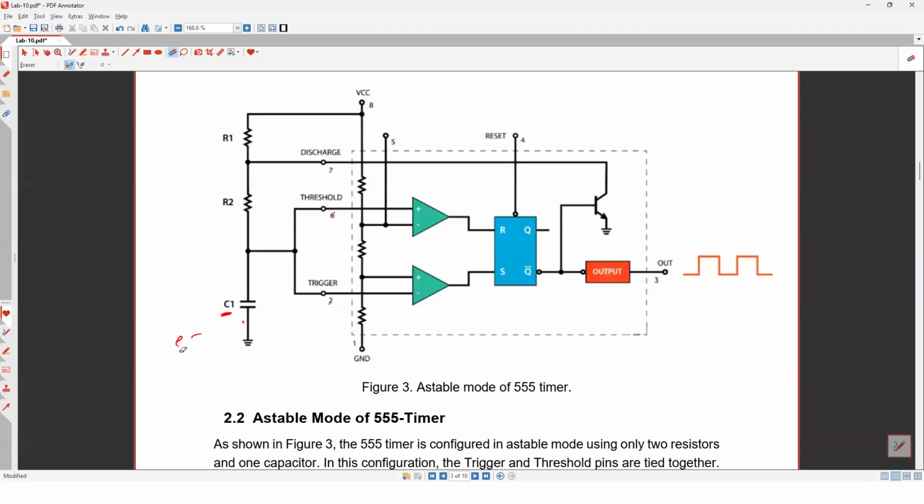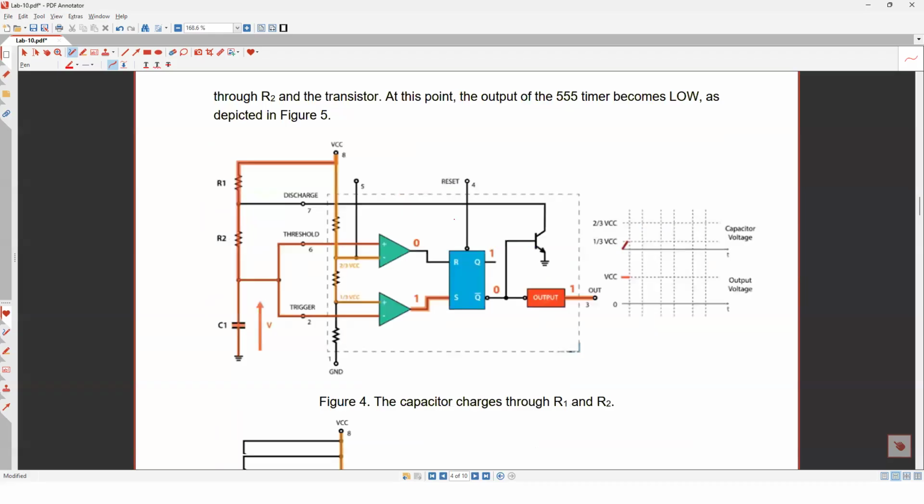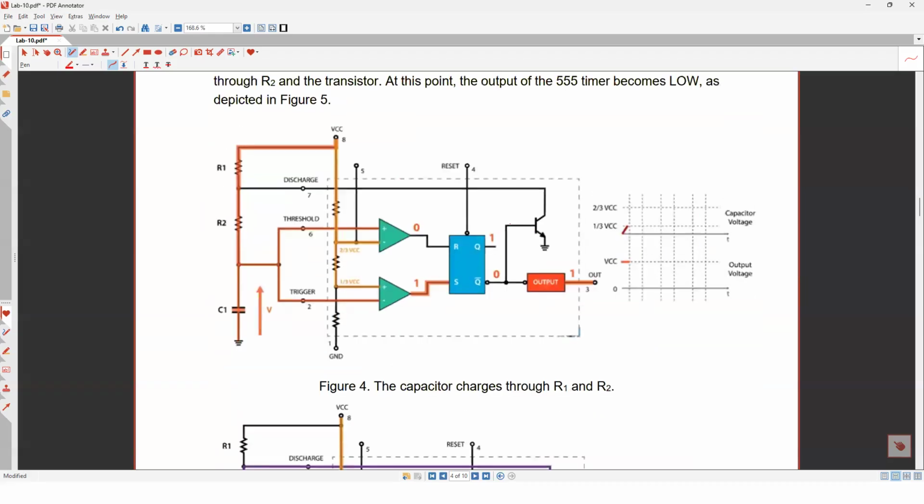Tell me how this circuit works. You are telling us this circuit here is a 555. That means if you just connect this resistance and capacitor, and I make a short circuit between pin 2 and pin 6, then this is what I'm going to see in the output. Can you explain to me why this can happen? What's the role of the comparator? What's the role of the transistor, and so on? That's what I'm going to explain right now. Very easy, it's not difficult. Very interesting. So look here, guys, how it works.